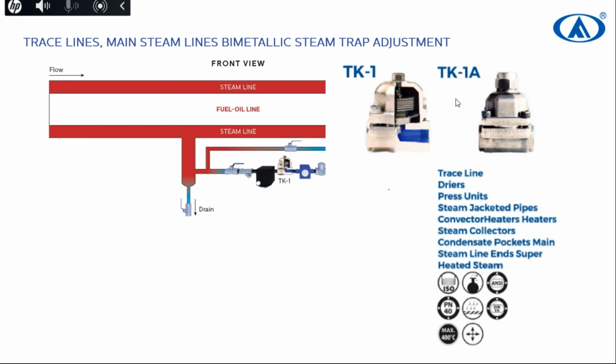For outlet pipe size after the PRV, if we use the same size as the PRV, besides affecting the downstream capacity, will it also cause high back pressure? If the same size is not enough, it will affect the downstream capacity, but it will also affect the velocity of steam.